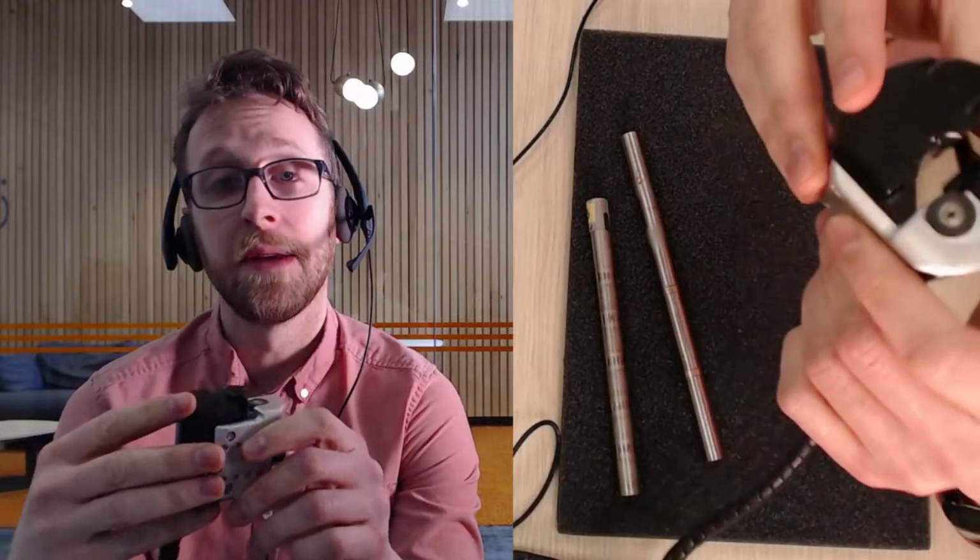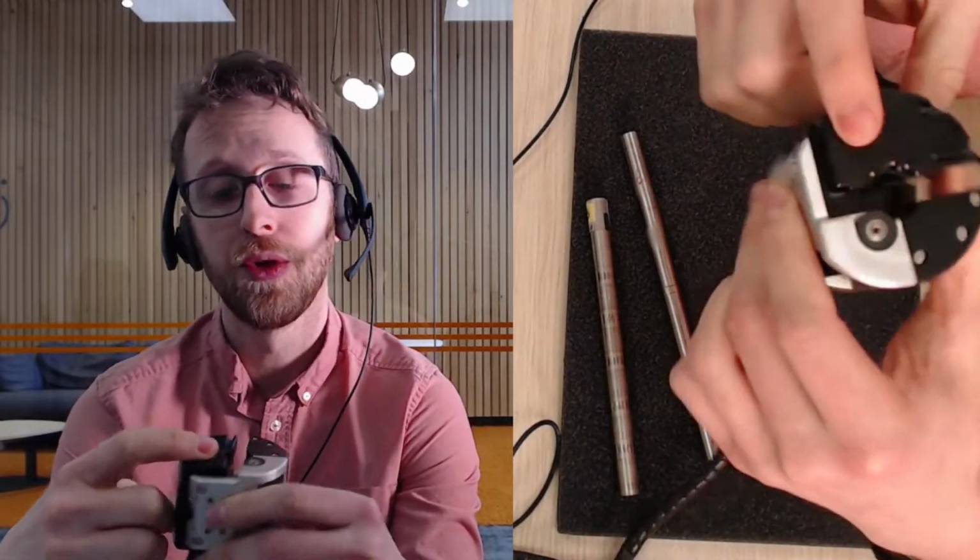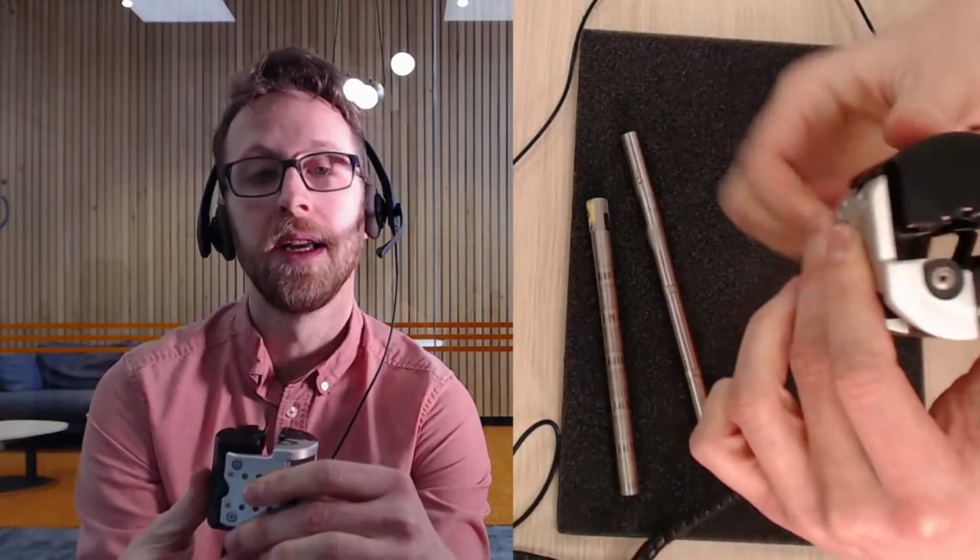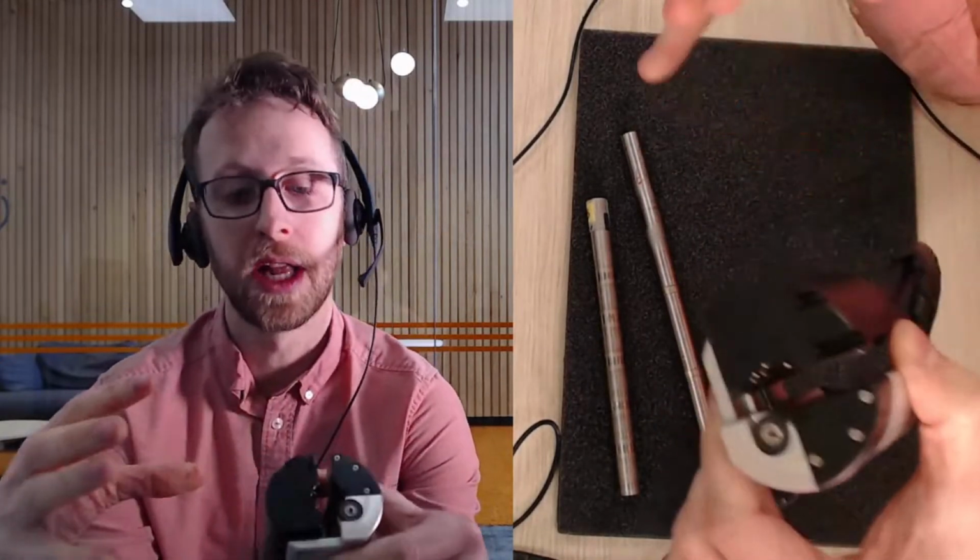The coils themselves sit inside a rigid shoe that is spring loaded. So if I press it, it is spring loaded, which allows that when you close the probe around the tube, it will sit directly on the array, and it allows a stable scan with minimal liftoff.